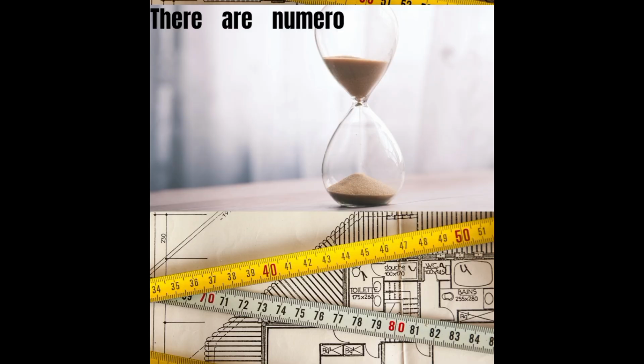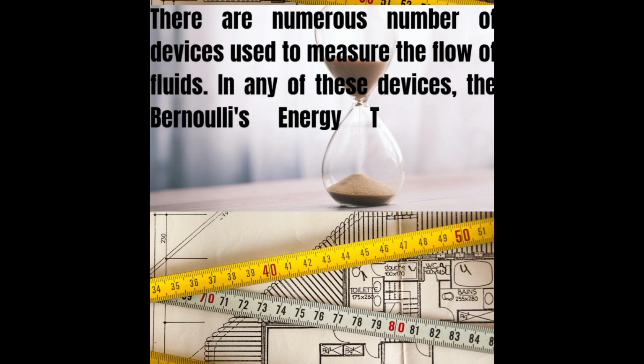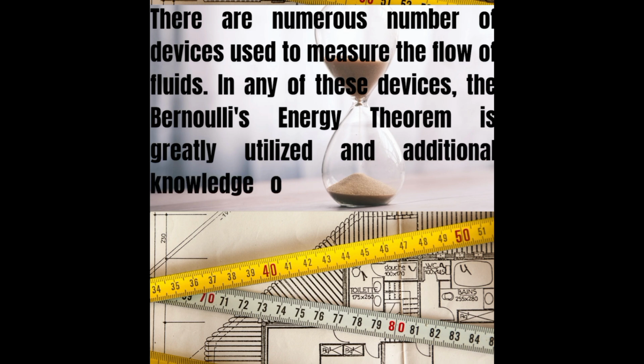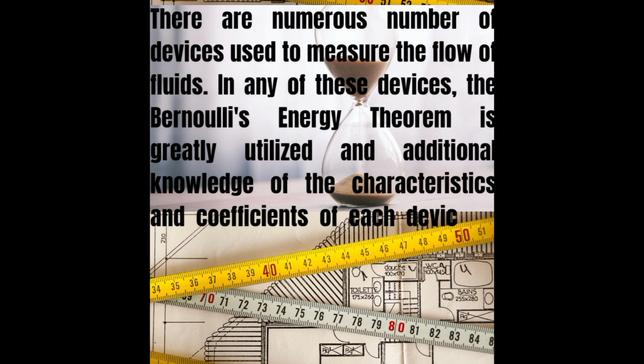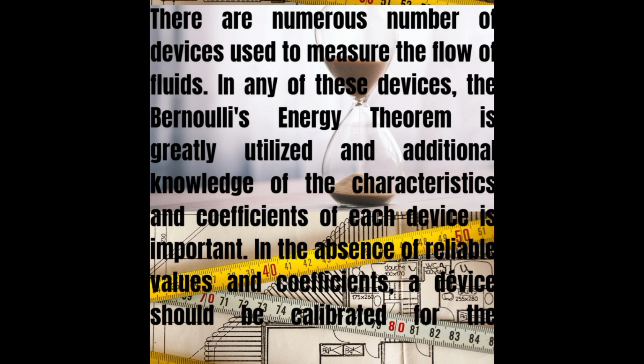There are numerous devices used to measure the flow of fluids. In any of these devices, the Bernoulli energy theorem is greatly utilized, and additional knowledge of the characteristic and coefficient of each device is important. In the absence of reliable values and coefficients, a device should be calibrated for the expected operating condition.